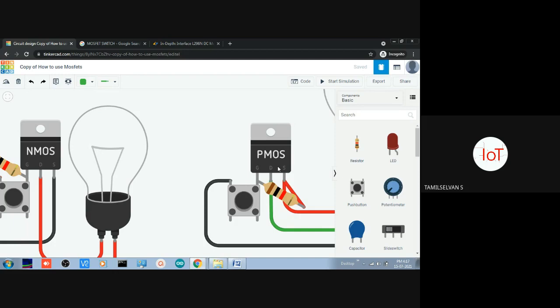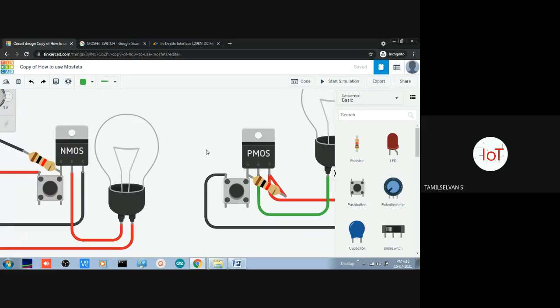For example, if you expect zero voltage perfectly zero and 5 voltage perfectly 5, in the sense combinedly you have to use. So PMOS is always good for high voltage, and high voltage in the sense logic high, and NMOS is always good for logic low value. So combinedly it will be called as a CMOS circuitry, complementary MOSFET circuitry. Whatever the circuit you are designing with, both the transistors will be called as CMOS transistors.